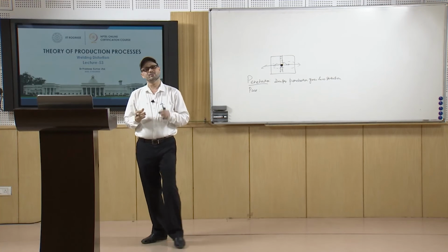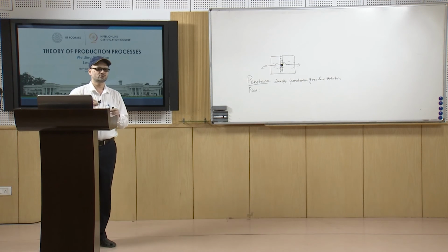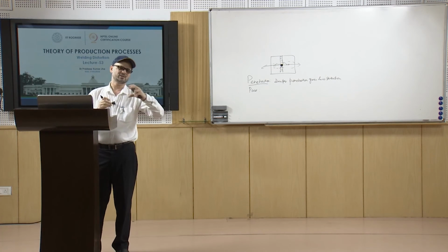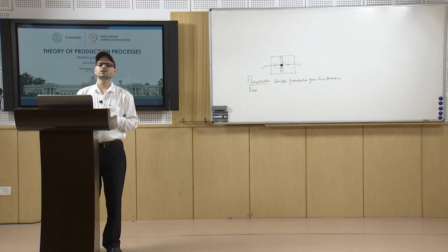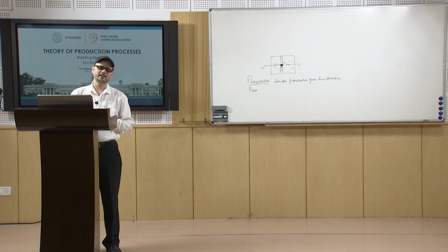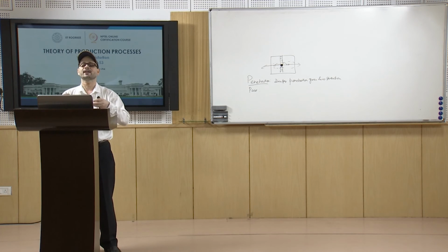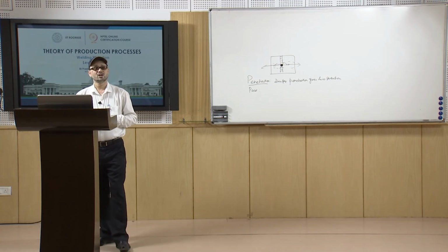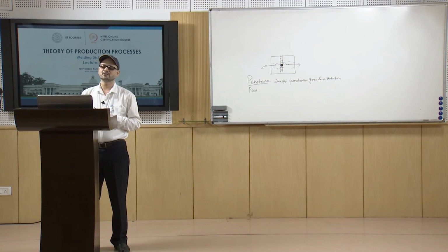When you use a straight polarity for thin plates, the work will be heated, and when you do the welding, these thin sheets are more likely to be subjected to that type of distortion. In those cases they cause this buckling of the sheets. Buckling, or twisting you can say, occurs when the specimen length exceeds the critical length for a given thickness. So, when you do the welding, the distortion which occurs is known as buckling.